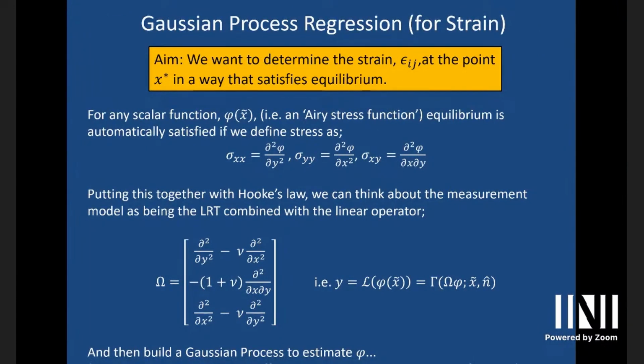So the Airy stress function gives the entire kernel of the equilibrium equation? I think in 2D that's true. I should be careful not to jump out of the bounds of things I shouldn't say, but I think in 2D that's true. There's three-dimensional versions of this as well, which I'll talk about in a moment, which are Beltrami stress functions, and they can be done as a full tensor that covers the whole gamut, or you can simplify it in different ways, and lots of people have. But I think in 2D that's true. Isotropic, yeah.